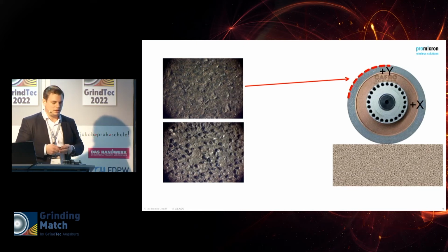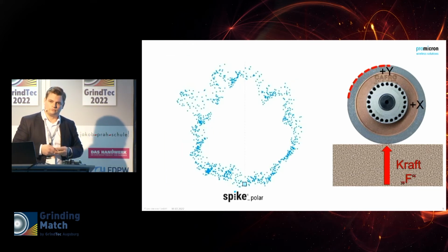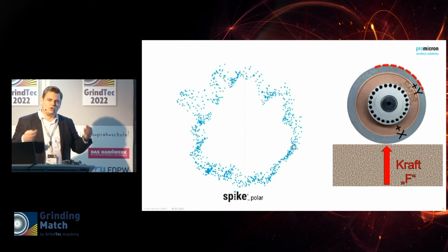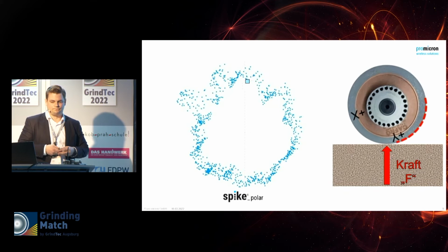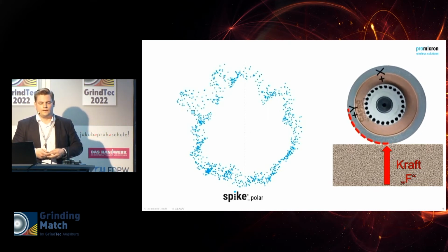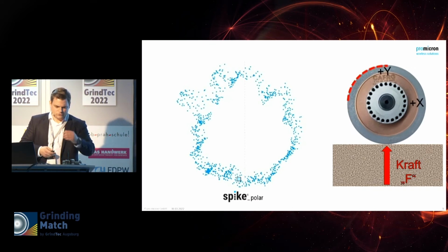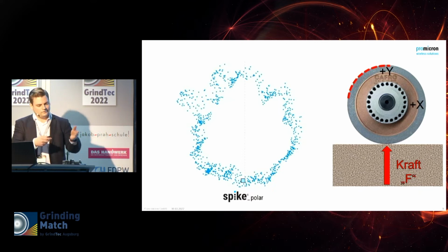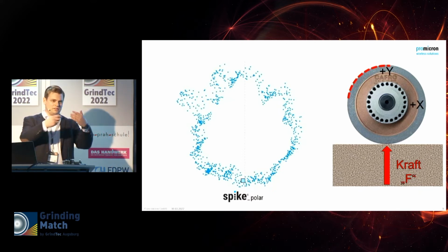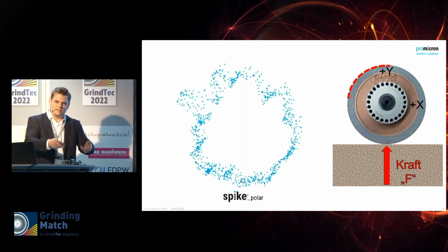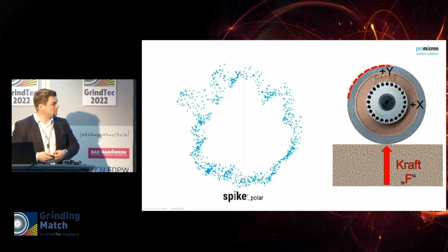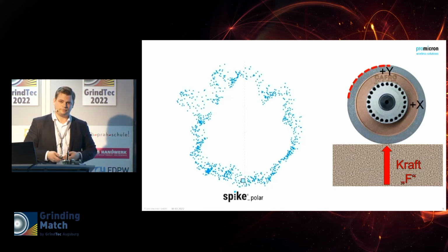And if in this area you have a material agglomeration, the picture looks like this. So actually, by way of the acting forces, we can cover this condition, and on the grinding disc we can also localize it. So that's the basic principle behind our measuring concept. The sensors are on the holder, then we have radio transmission, of course, to the receiver connected to the laptop. You can pick up the measuring data, change something in the process, recapture the data, and you can have an influence and you can compare.